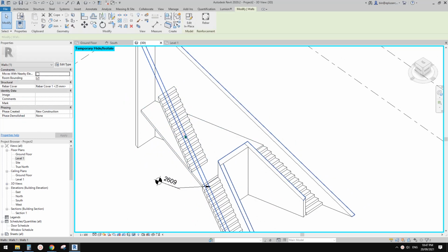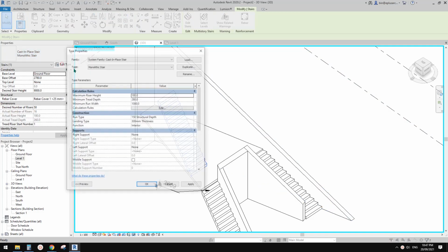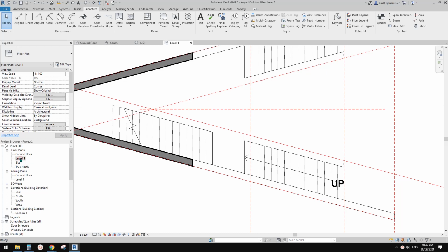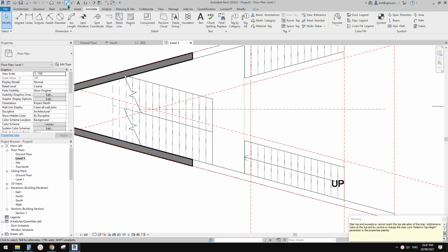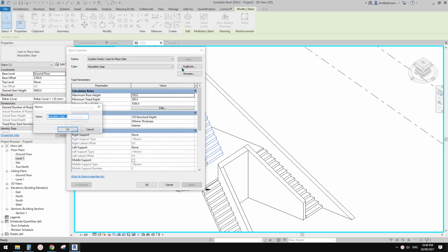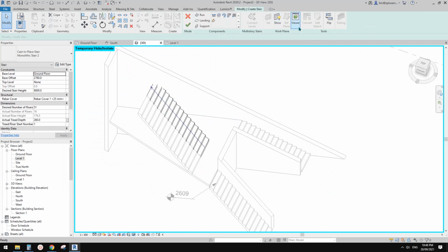Okay, so first select this stairs. So we're going to create a new one. So edit type, create similar. So CS, create similar. Or hang on, maybe we can just copy it. So let's go to elevate floor plan and copy this one next to it and go back to 3D view, select this stairs, edit type, duplicate, create a new, and this time I'm going to change the, so actually let me just leave it for now because we're going to edit this sketch first.